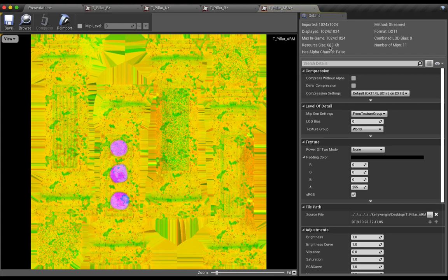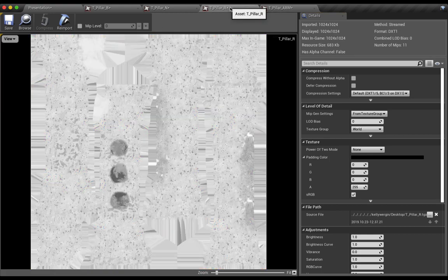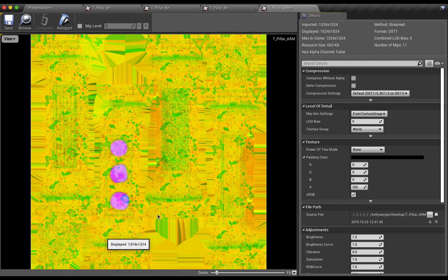It is half of a meg, but I have all three of these textures in, where for half of a meg, I was just getting the roughness. And that's if I change it from the compression setting that it comes in by default. The only thing that you need to do when you are bringing in multi-maps is uncheck this gamma correct so that it doesn't damage your grayscale textures.